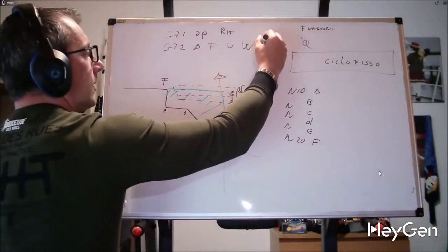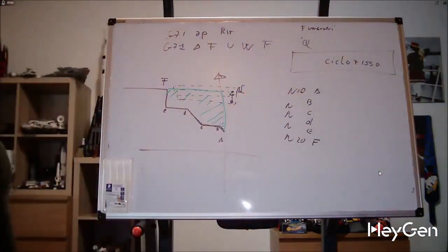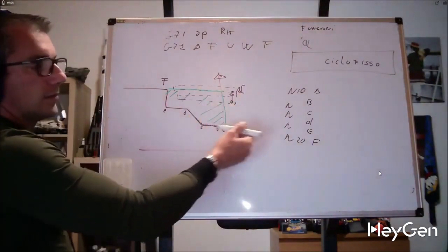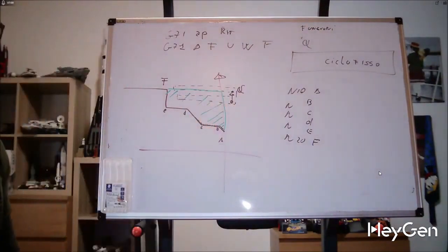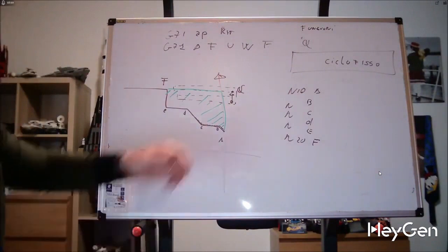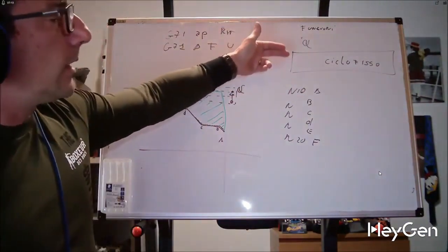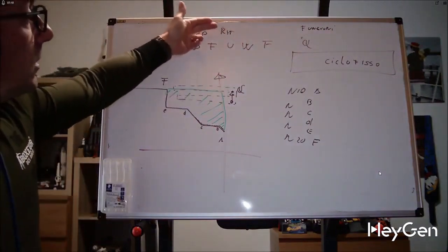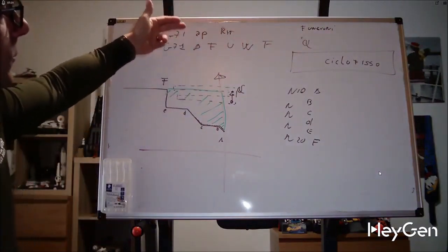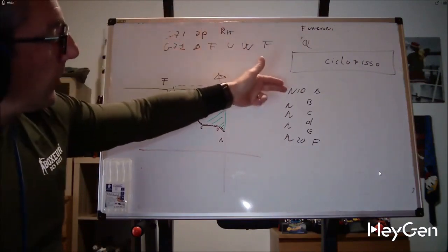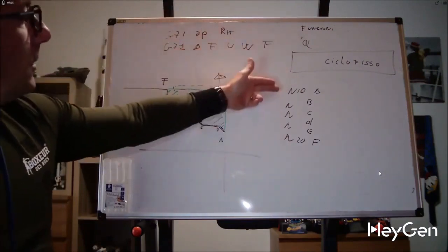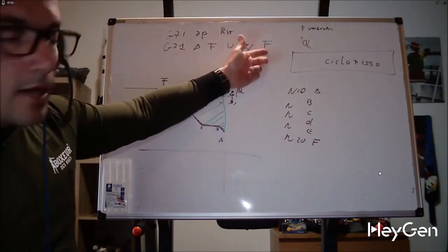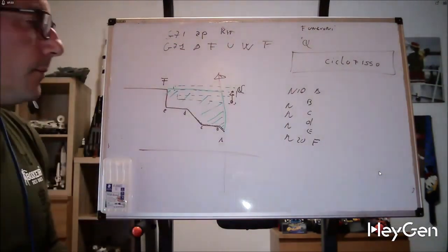Then I'll specify the feed rate, which will be a single feed rate for the entire cycle, with which we'll make these passes. So, the machine will read preparatory functions, then it will say, I have a fixed cycle that I will have to do with a 5 mm pass, returning by detaching myself by 1 mm from the tool, following the profile that I will describe in the following blocks, between block 10 and now block 20. I will have to do everything at an F of 0.30, 0.20, 0.40.